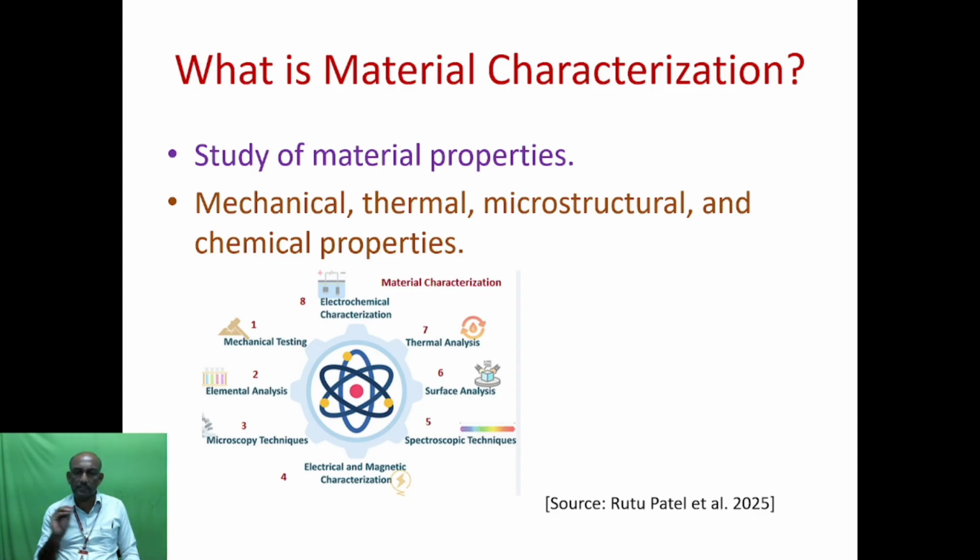Not only the strength aspect, in the thermal aspects also, thermal conductivity and creep strength. These are all mechanical and thermal material properties. To study them, we have to characterize the microstructure of the material. Microstructure means we have to analyze the grain structure: how the grain structure is dislocated from one point to another, and any dendritic or laminar structure and intermetallic compounds formed in the grain boundaries. From that microstructural point of view, the material properties will vary for that particular material. If we go for some heat treatment process, that is aging heat treatment and solution heat treatment, the grain boundary structure and intermetallic compound formation and distributions will be varied.